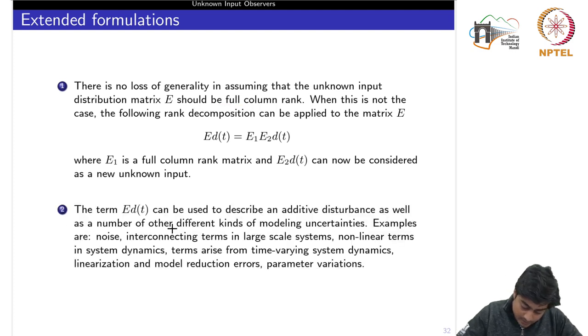Second, which is pretty important, the term E times d(t) can also be used to describe an additive disturbance, as well as a number of other different kinds of modeling uncertainties. One of the examples we will take up when we come to the tutorial is how you can model some uncertainties and disturbances which are non-linear in this LTI system in terms of u and y.